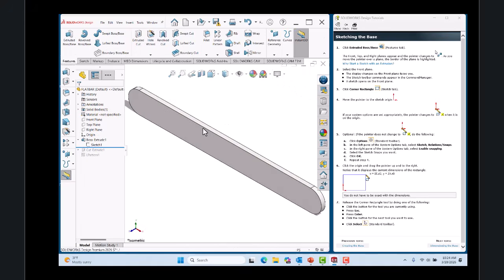So I'm going to get out of this sketch. My favorite shortcut key is Control-7, which goes to an isometric view. And then I'm going to show you the first cut that I did with this feature. I'll expand to show you the sketch that I used with the dimensions. And also, if I drag the rollback bar down all the way to the end, I will see the linear pattern.